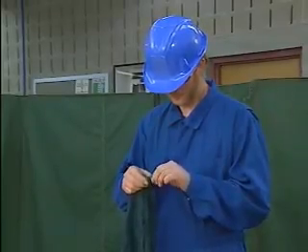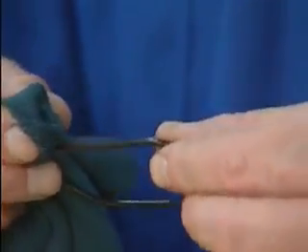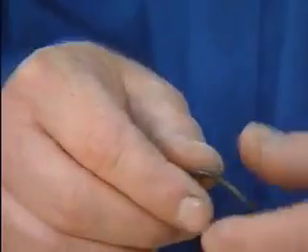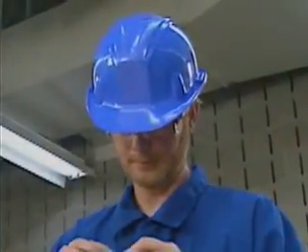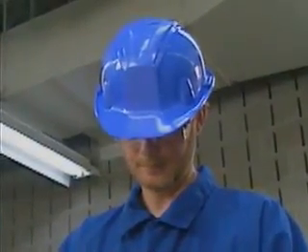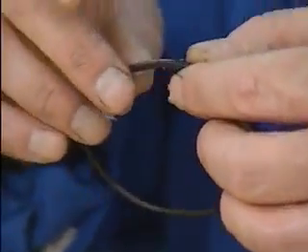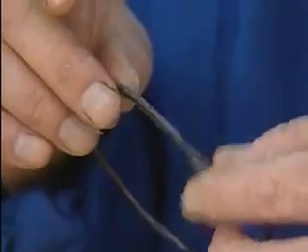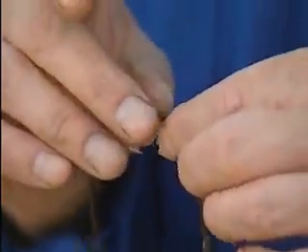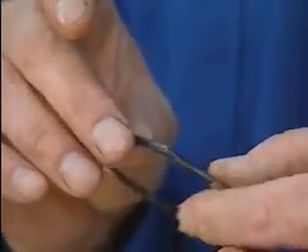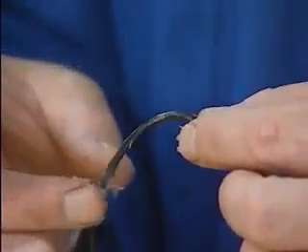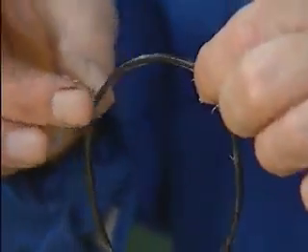Many O-rings, due to their rubber composition, have a tendency to stick or bind to metal sealing surfaces. Lubricant is often used to allow the O-ring to seat more easily during installation. The lubricant that's used must be compatible with the fluid in the system and with the material that the O-ring is made of. If the wrong lubricant is used, the O-ring could react with the lubricant and be damaged.